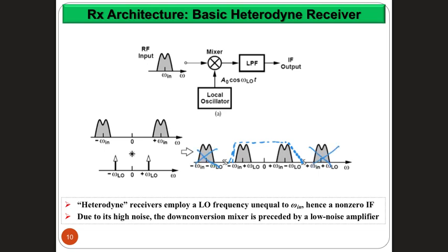So the end result is I'm going to move my signal to a lower band. Now I can do better selectivity in terms of channel selection, and I can suppress some of the local carriers around me, the in-band interferers adjacent to me, so that I can deal with the signal more appropriately.